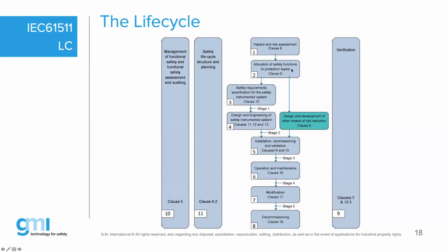They're going to go conservative and say, listen, we have done phase number 1. Let's take the risk matrix, and we're going to go 1 cell higher in our cell matrix than what we actually would need. That means skip this calculation, go straight into the SRS, and the SRS is there. That's another webinar which we have done already. The SRS will define what do we have to build additionally to reduce the risk.